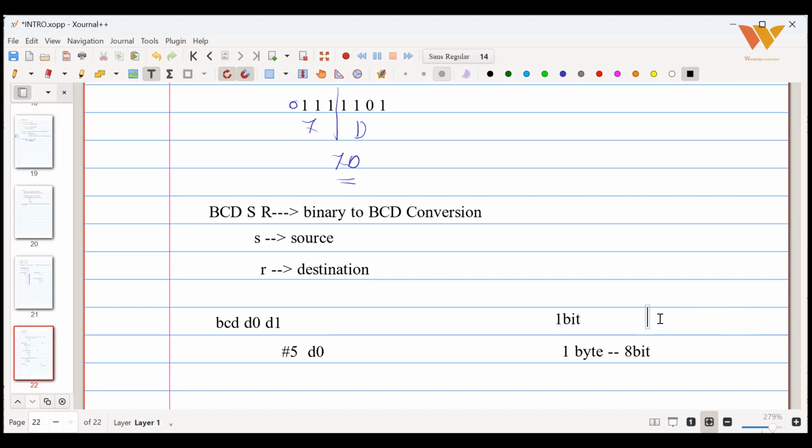Madam, actually input address 0.00, how much is the maximum, a total of 16 inputs? No, it depends upon the PLC which you're selecting. Let's say I'm taking an Omron fixed type PLC, CP1E model, I'll have 6 inputs and 4 outputs. So the address varies from 0.00 to 0.05. So that is 10 IO. If I take a combination of 20 IO, then it is 12 inputs, 8 outputs.